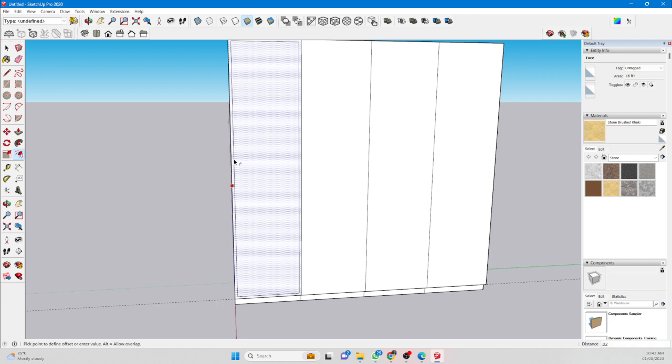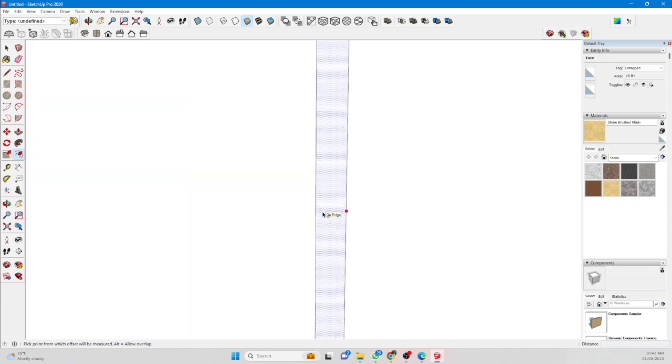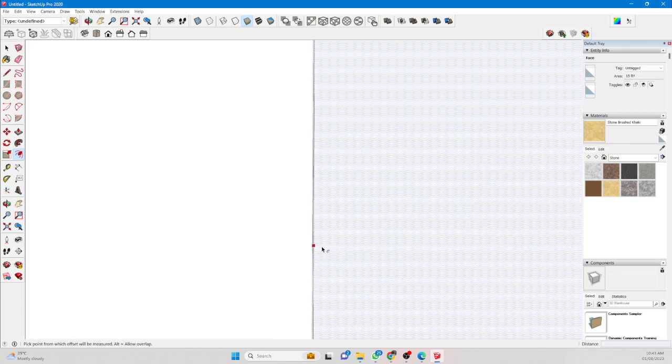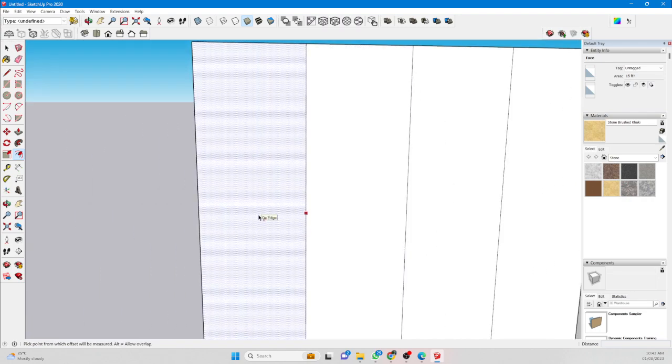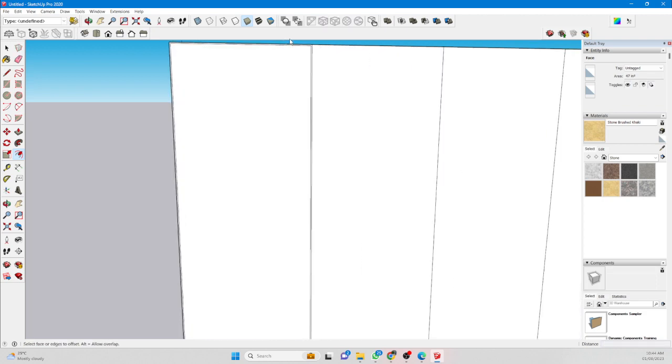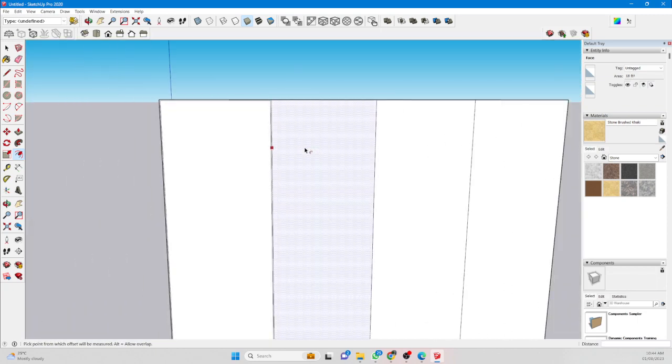So we'll give 0.02 inches. 0.75 is the thickness of the door. The gap is 0.2 inches. See here, I'll show you. Otherwise you can use 0.2 inches. So for every door we'll double click with 0.2 inches.